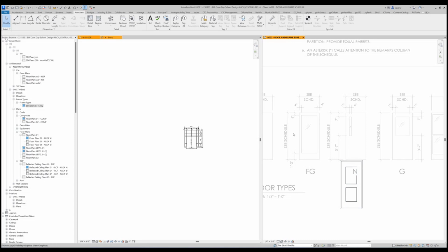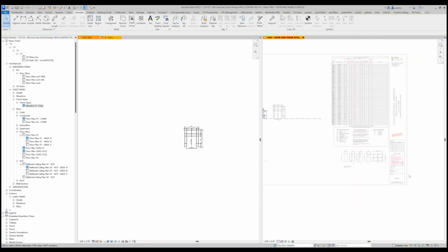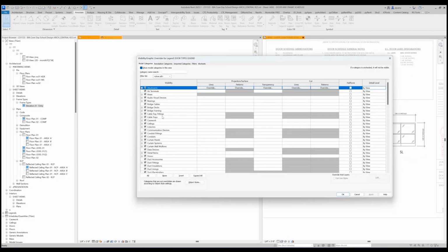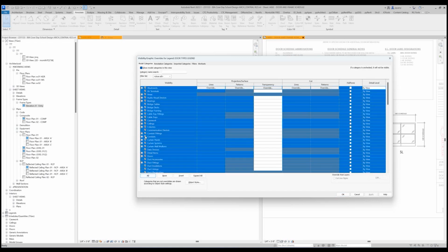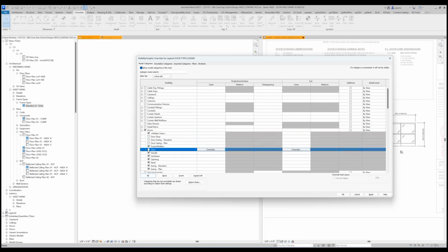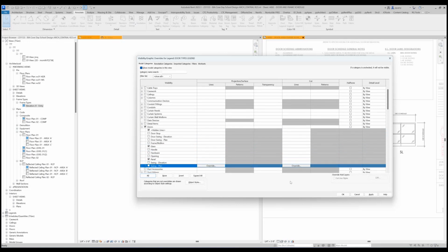So this view basically needs to be set. Well, I'm doing it in the wrong one. First of all, I need to be in this one when I do it. So component, door frame FG2. Problem is I've got to turn off everything now except for the doors and then the subcategories. And this should be all set up before you guys get in there, but dressing plan, frame, no frame, glass is fine, no handle, no hardware, no opening, the panel's fine, no swings.